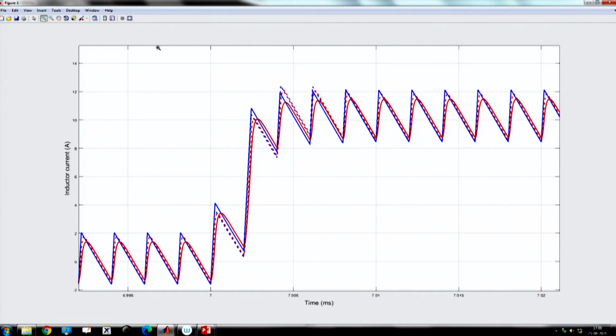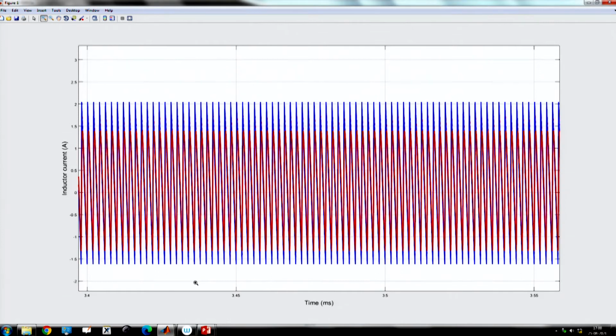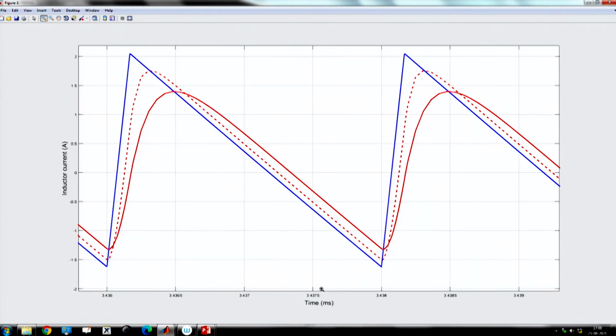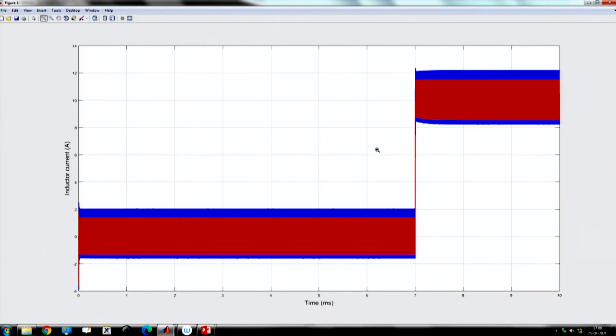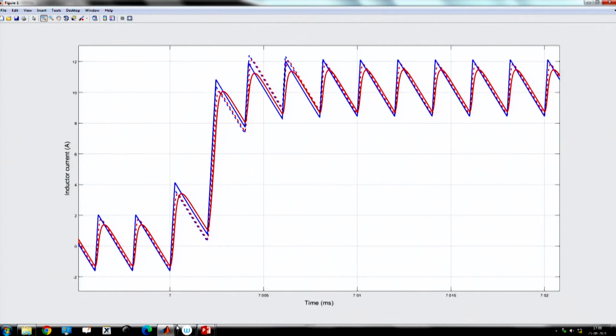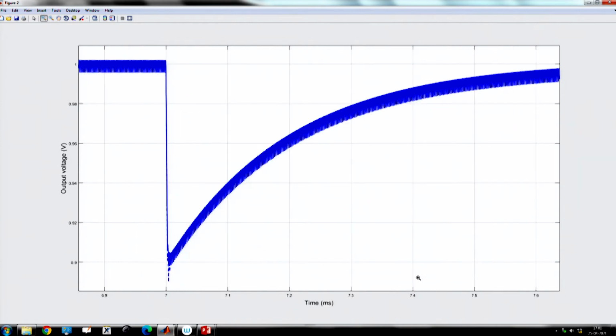So, the transient response is slowly getting affected, and you can see the solid line which further reduces, that means your bandwidth is reduced further, and your response still is not drastically affected, but yes, somewhat it is affected, okay, and this will be reflected in the undershoot of the output voltage.